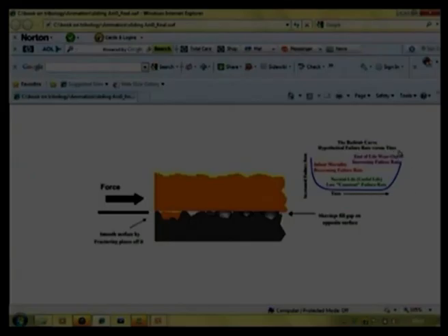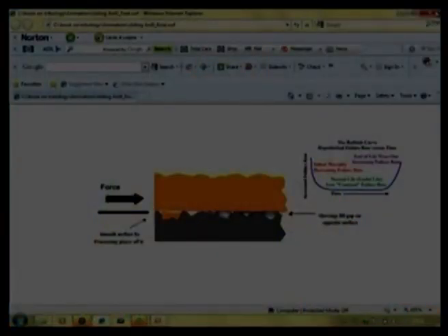So, we are more worried about this end part to estimate what will be the life of the component, and about this steady part, which is going to tell when the component is about to fail and what will be the maximum life which we can achieve. This is a hypothetical curve; not every wear curve will be like that. There is a possibility of continuous increase in wear rate, it will never be in a steady state condition. That is why we need to understand wear mechanisms properly.